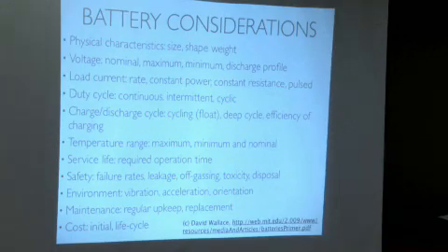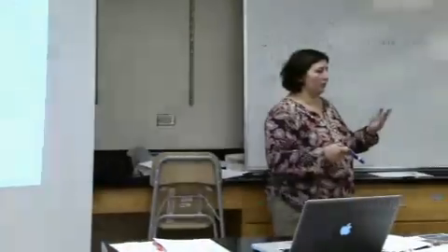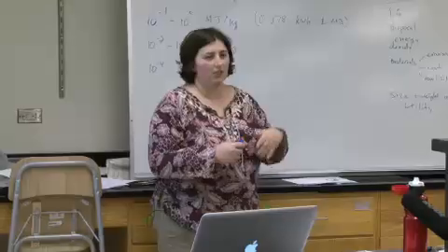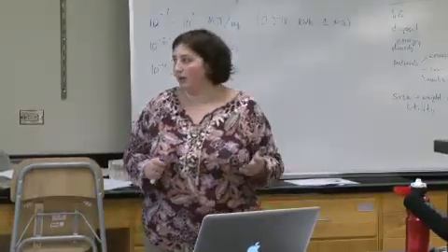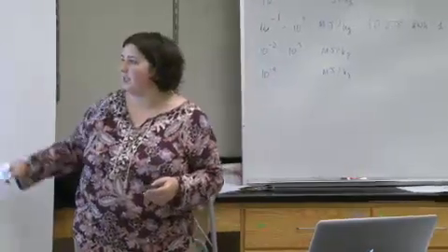So that means if you're doing anything complicated, you can't just use a battery. You also have to use some sort of charge controller or discharge controller so that you never discharge your battery too much and you never overcharge it, and all these subtleties. So batteries are really useful, but there's a lot of details to worry about.